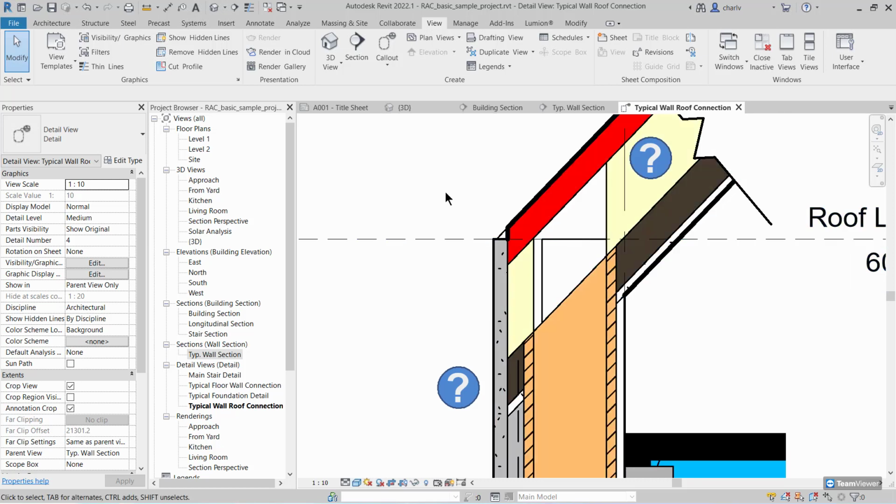If I show it in color, you'll see there's the yellow truss, and that piece is taken away using the cut profile. So that just changes the 2D view of the 3D model. It doesn't change the truss in 3D.